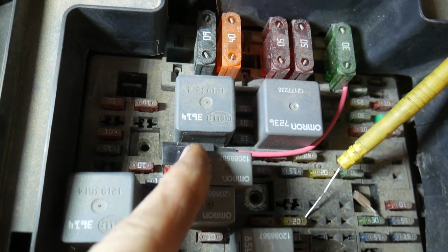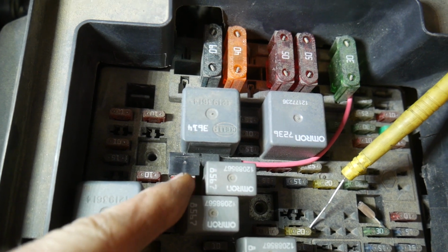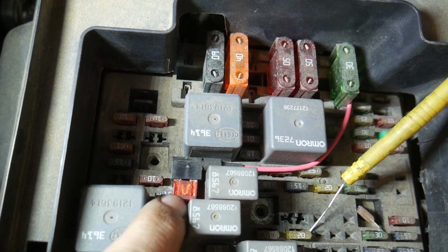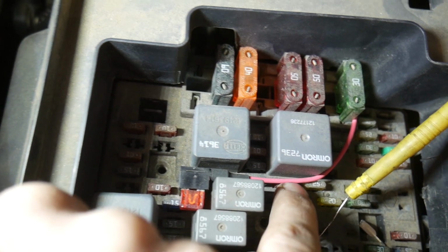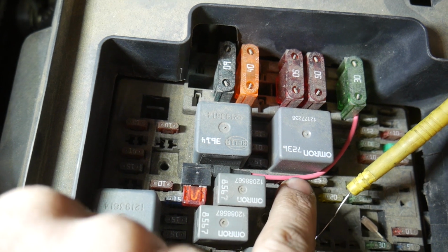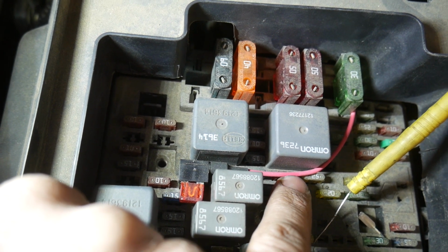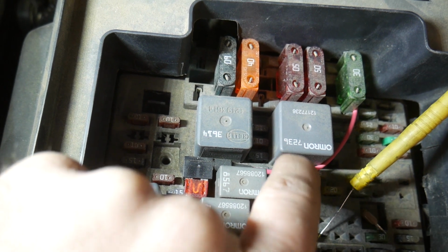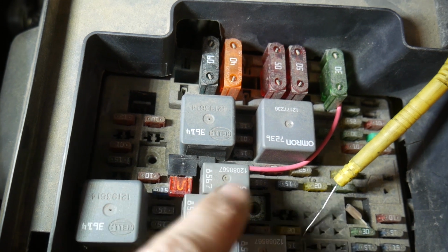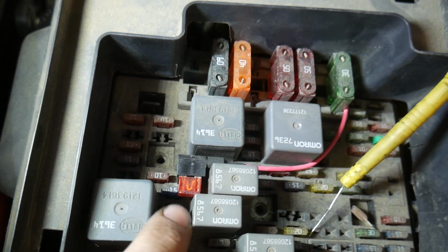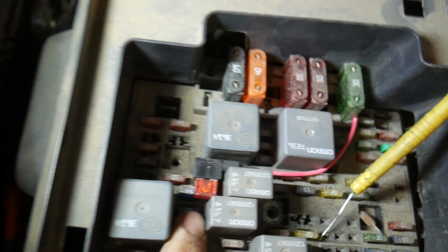If the power's coming in on this side, it has to go through the primary fuse before it can power up this accessory fuse. So now, let's say, and they're both 10 amp fuses, if I have, we'll say a 7 amp load on this accessory fuse, which this wire is actually going back to the trailer wiring. I'm not sure why they decided to tie this in here. So if this is pulling 7 amps when they have a trailer hooked up, it's also putting that 7 amp load on the lower fuse.